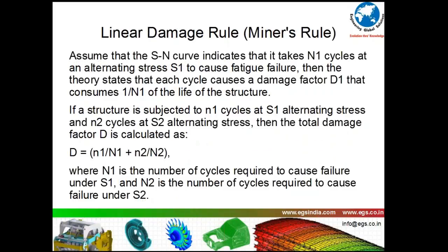So, if we have different events occurring for our product during the life cycle of the product, we decrement the life from 1 all the way till 0. If the life crosses 0, for rotating components, and comes into the other side, then the object has failed. This is the condition that we look at in terms of fatigue failures over there.